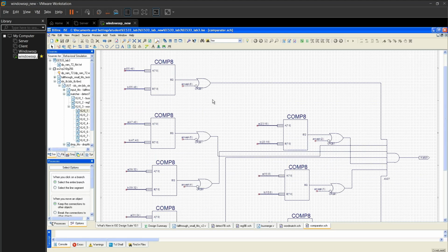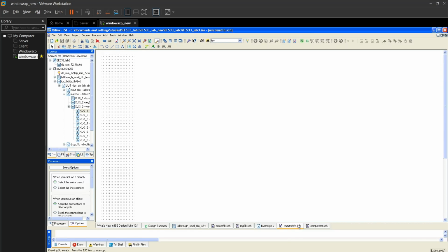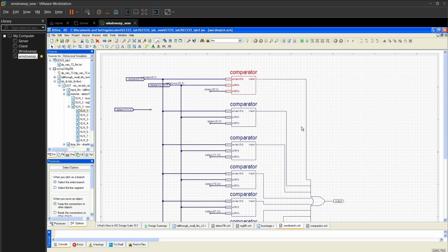A mask helps in checking which byte needs to be checked. For example, if we don't want one of the bytes to be checked, it by default goes in as one and shows as a match. This ensures that we only check the bytes we require, and bytes which are not required can just pass through.